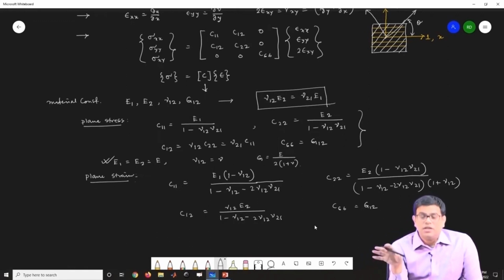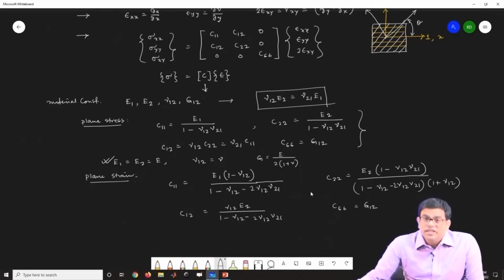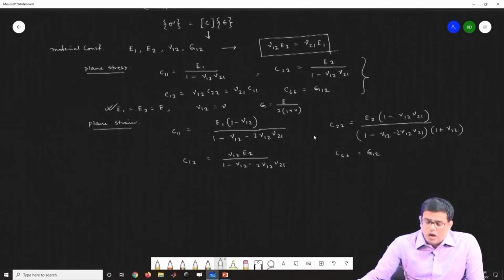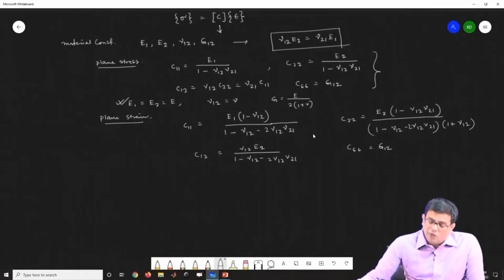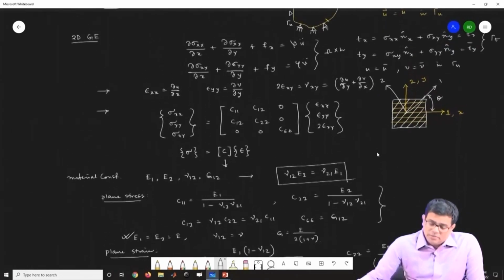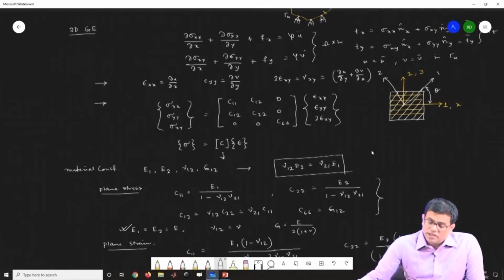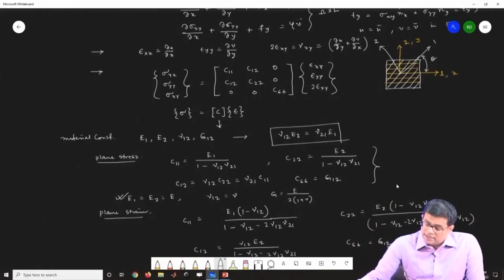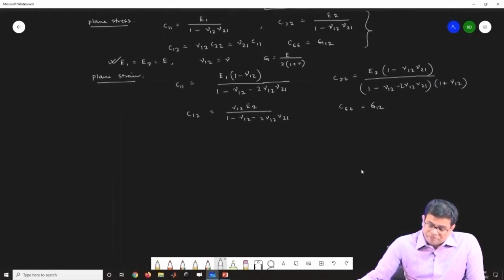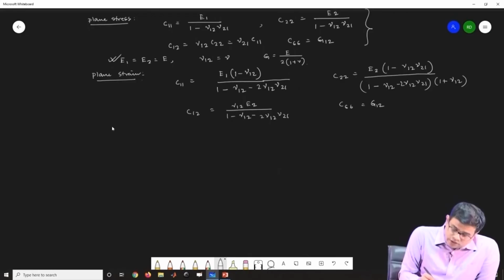Displacements are two dimensional here, so displacement is a vector now, that is u and v. So it is a 2 degree of freedom per node problem. Now if I substitute this kinematic and this constitutive equation into the equilibrium equation, then our governing equation looks something like this. So let me just write it.